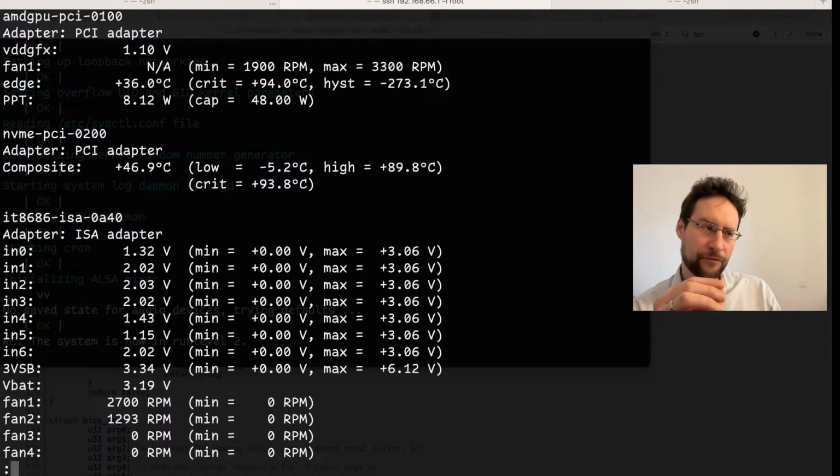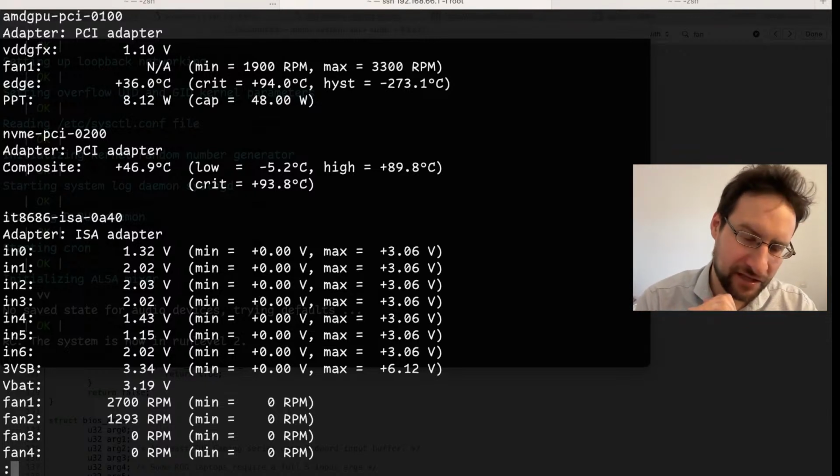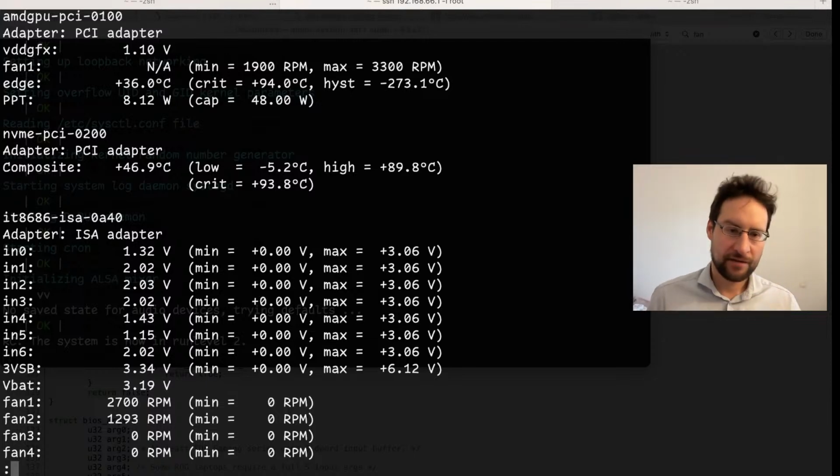With DDR4, you only had a temperature sensor for very high-end memory, but for DDR5, my understanding is that probably all DDR5 on-DIMM memory voltage controllers have a temperature sensor inside this hub IC, so even if it's not precise, at least you have some kind of reading, perhaps 5 degrees less because of the offset in the middle of the module. I would like to have that. I tried to get that to work some months ago, but it didn't just work due to too many changes. But anyway, there you have it.